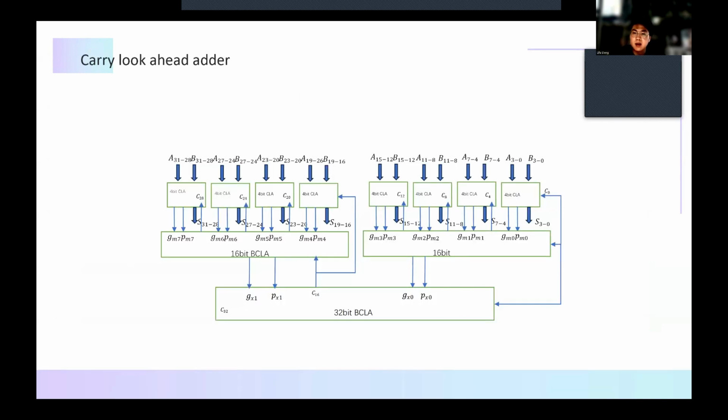multiplier. If we want to design a high performance 32-bit adder, we can theoretically generate all Si and Ci at the same time. But this makes the circuit structure very complex and greatly increases the fan-in and fan-out of the circuit, which is not feasible in actual design.